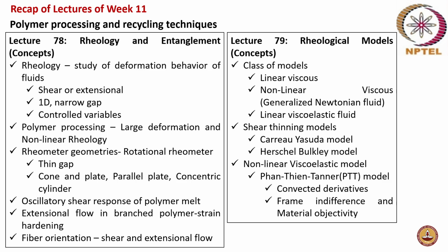Next, lecture 79 was on rheological models. This was again on concepts. So, what are the different classes of models? You have linear viscous, non-linear viscous models. Linear viscous, you have your Newton's law of viscosity, where shear stress is directly proportional to shear strain, and the constant of proportionality is your viscosity. In case of non-linear viscous, where you have the generalized Newtonian fluid, you have viscosity replaced by an apparent viscosity, which is not a constant but a function of shear rate itself.